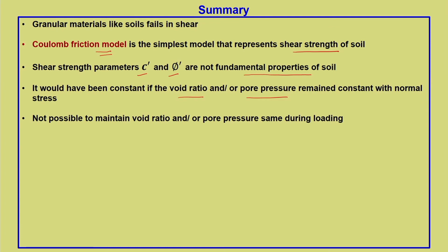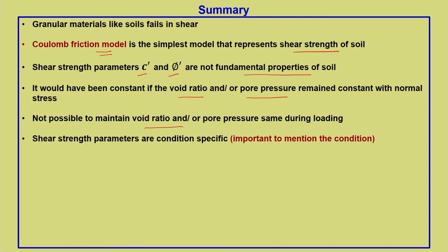Now, if the shearing would have happened at constant volume, probably C dash and phi dash can be fundamental parameters, which we are not able to achieve. Either the volume change will happen or the pore water pressure would change. So, this prevents the phi dash component from being a fundamental parameter. It is difficult to maintain this constant during loading.